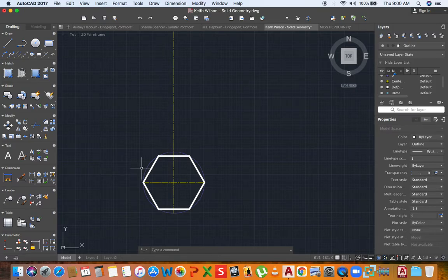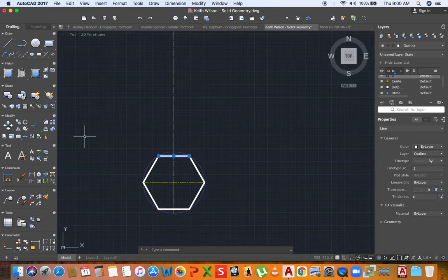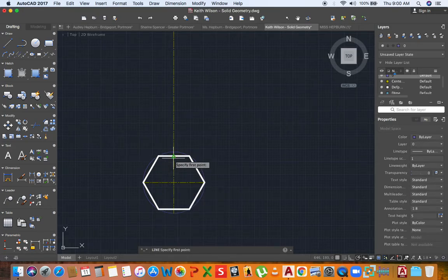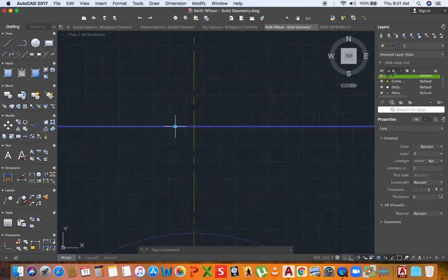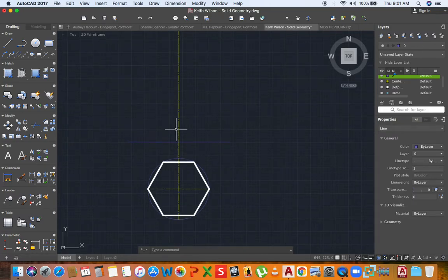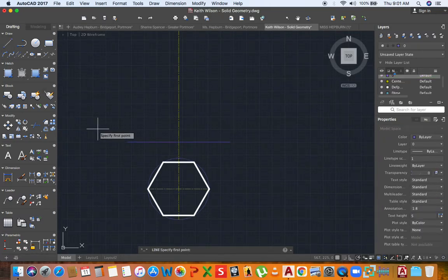Right? After drawing the hexagon, you need to draw the piece in the middle, the truncated portion. You cannot do that as yet until you have drawn the front view. So I'm going to project some lines. But the first thing I'll do is offset this line, or rather draw a line up 20. That is the spacing. Then I can now proceed to draw another line going across. I can now delete this line and pull this line across as well. I like to center the line, so I'm going to click on the line, pull it to the center. You don't have to, but it leaves for less errors some of the times.